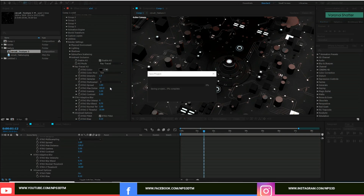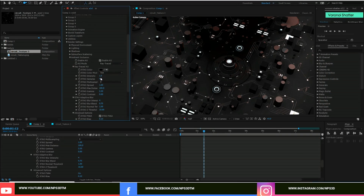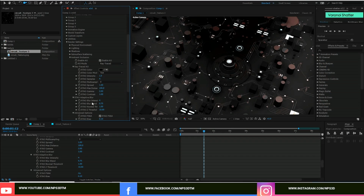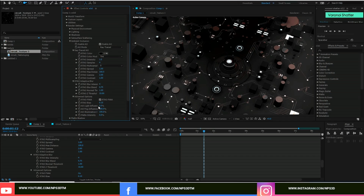Intensity 1, maximum distance 145 actually. Let's make it 100. Ray trace samples 2, contrast 1. Fine, it's good now. And here is one more option, AO light influence, make it 100, 1000% or just 500.